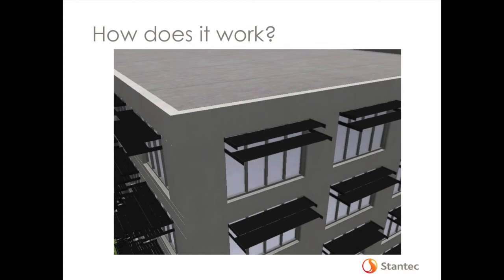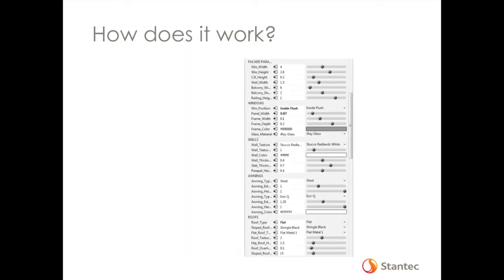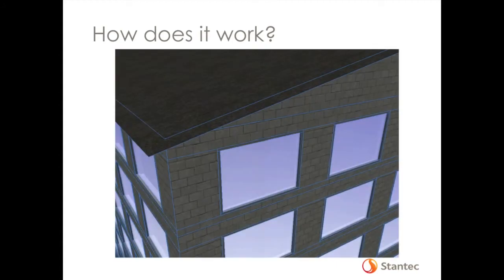Detail of it is really as advanced as you want it to be. This is a zoom in on that building rule. So right now, it's actually got rules for height of building, height of eave, the parapet height, whether or not you want eaves, the type of window. So just by changing a couple parameters in that as well, you can now make it with a different type of roof, different type of window, different type of sill, and basically no overhang for the eaves. So highly customizable rules. And really, it's as much as you want to customize them, as much detail as you can get into these rules.